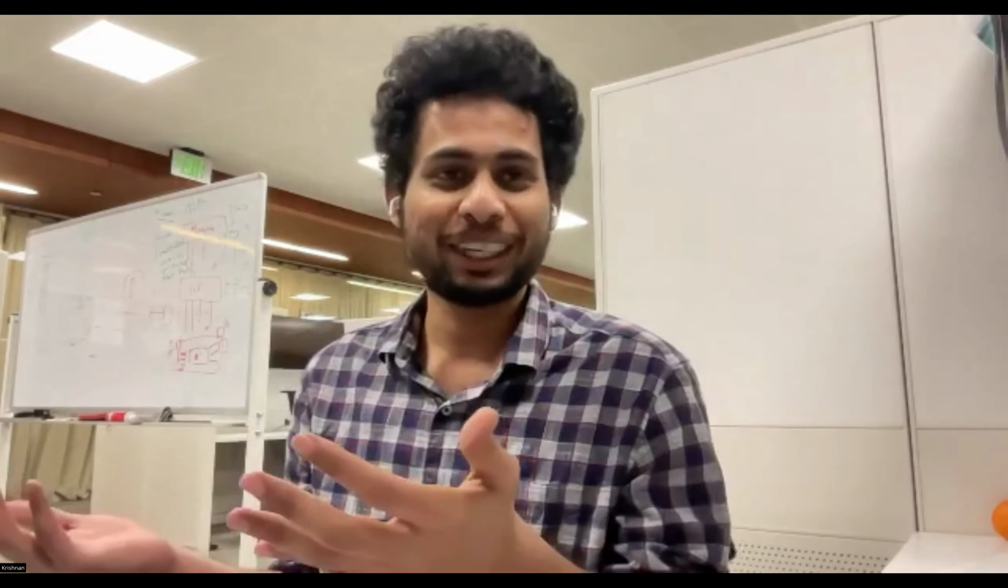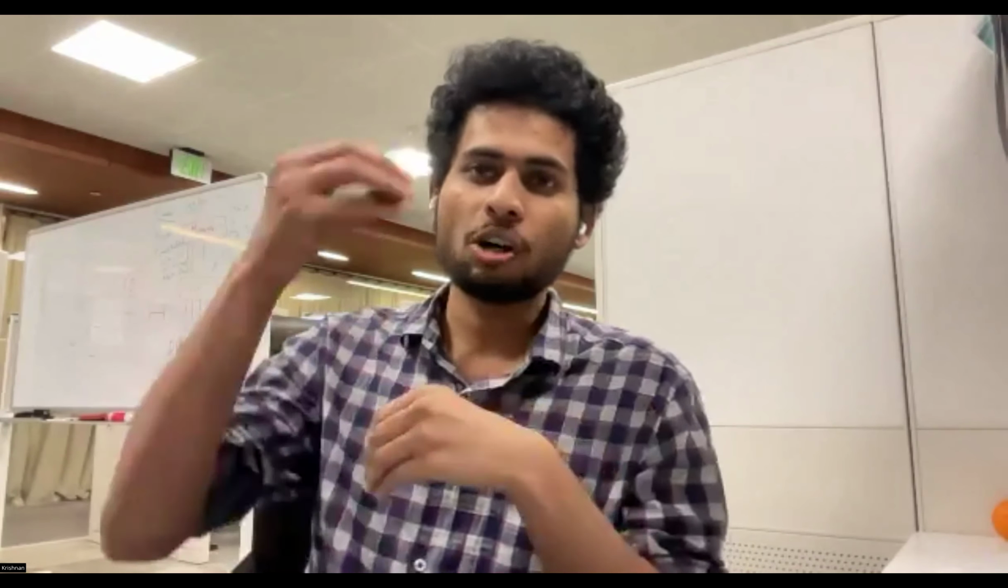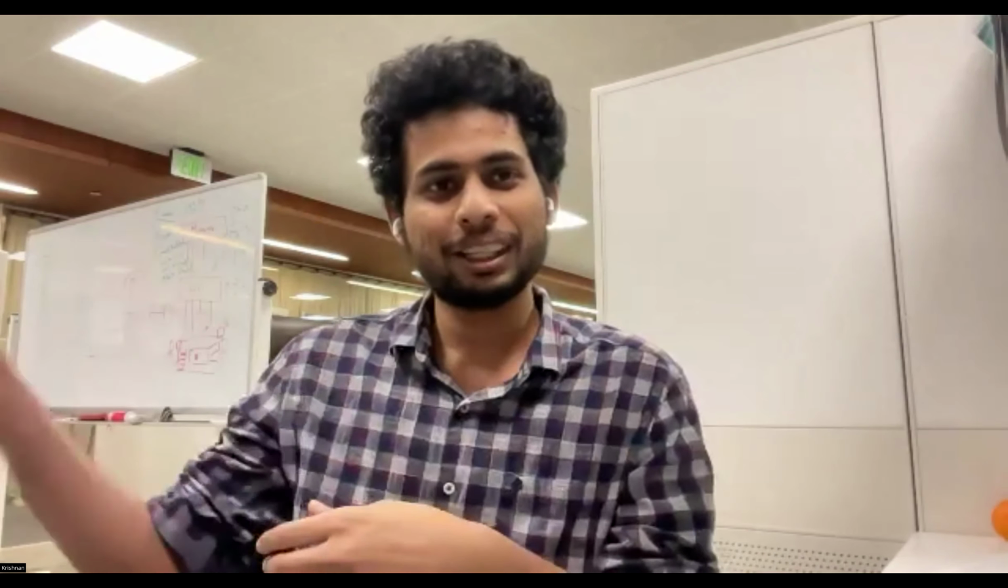The same thing I was trying to do, if you remember. So I solved it, but in the end, I had to write my own FIFO with independent clocks, because the AXI FIFO from Xilinx kind of doesn't really work; I don't know how to make it work. I think it needs a locked phase or something like that to really get something out on the other side.